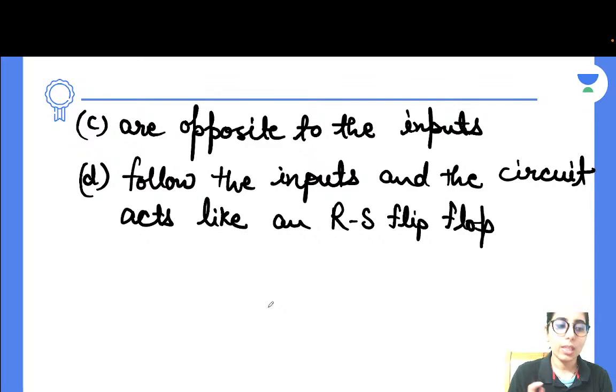So if you have a clear idea about the circuit and you have prepared the flip-flops, you can easily relate this part. It's more about the circuit. But since the RS flip-flop gives you a forbidden condition, just to remove that condition, we make the changes. One of the outputs of the RS flip-flop, we take it back to the other side input, and the other one we take it back to the other side input.